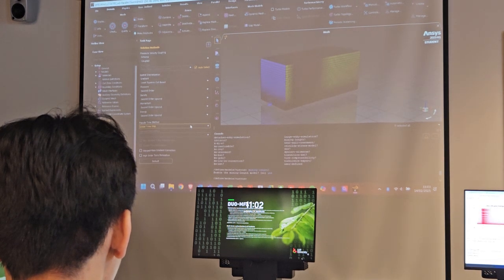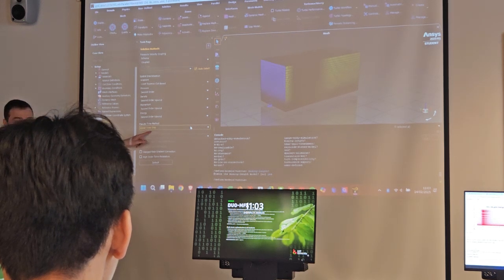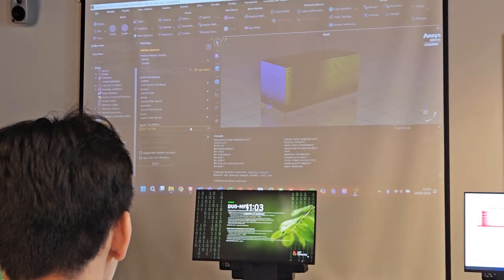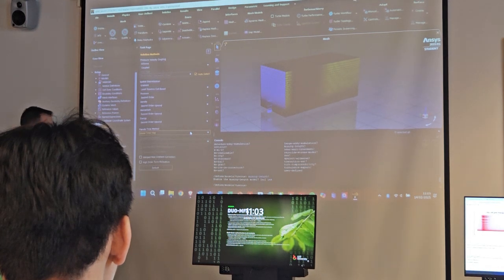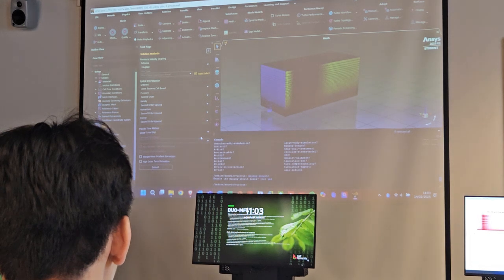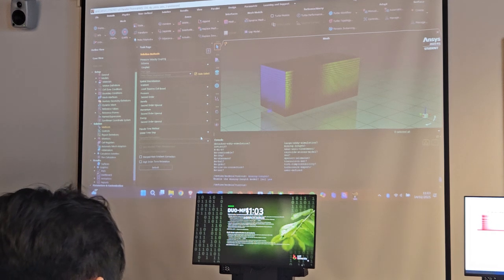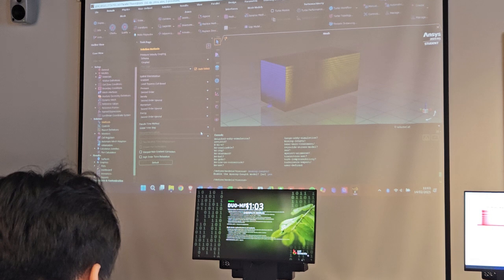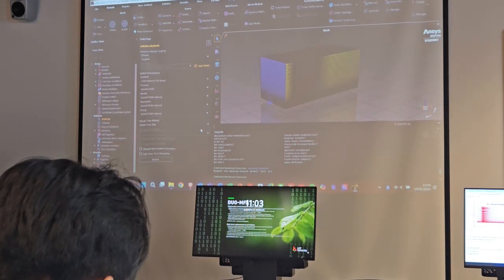And then, in this version, the pseudo time method, I use a global time step method. So what this means is that I'm solving the governing equations, so continuity, momentum, and energy, in a transient form. So I have a transient term in the equations, but it's not a real transient, it's just how the solution is iterated, how the iteration is going towards a steady solution.